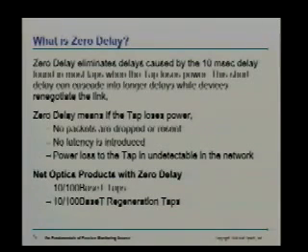So zero delay is really a way for you to make sure that you can pull power from a passive access tap all day long and never disturb the network link, not lose a single packet on the network. You will find zero delay in 10/100 copper products. Yes, it's kind of a legacy system, but we all typically still have 10/100 copper links available to monitor.